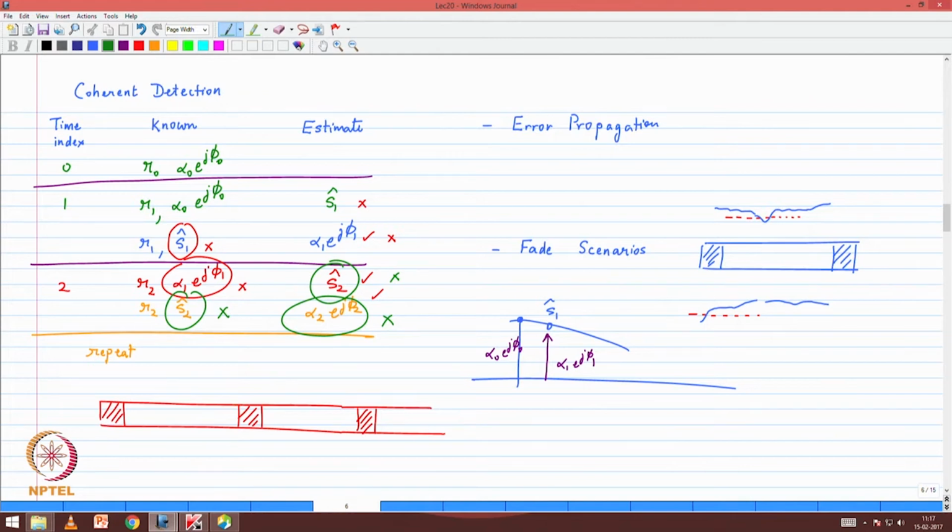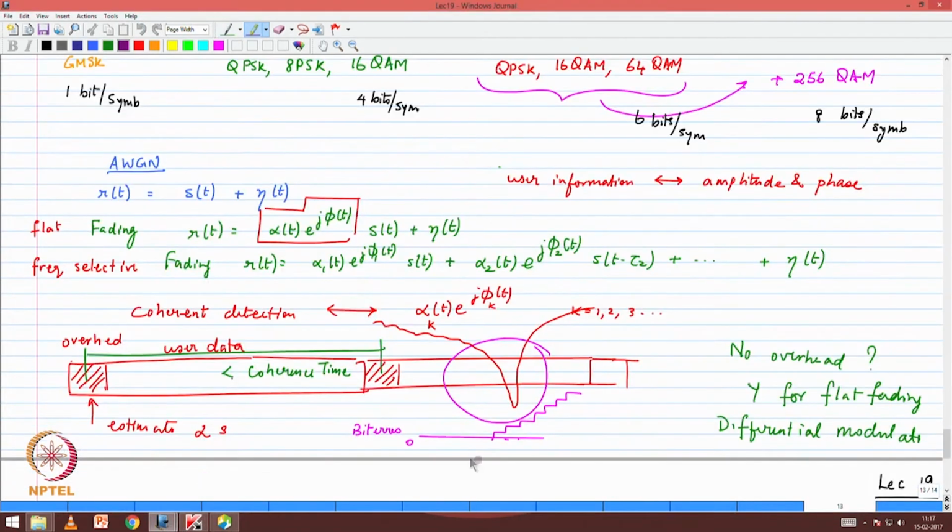Now this is what we are worried about, because between these two channel estimates, let's call this channel estimate number 1, this is channel estimate number 2, let's say that the signal momentarily went into a fade. All it needs is for you to make one symbol error, and then slowly the error builds. So the detection errors was what I had drawn in the previous graph. The bit errors, no errors until you got into the fade situation.